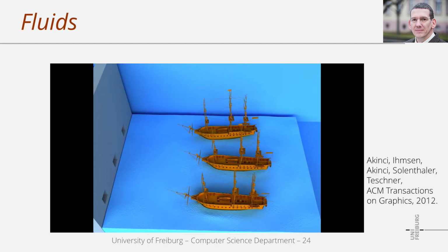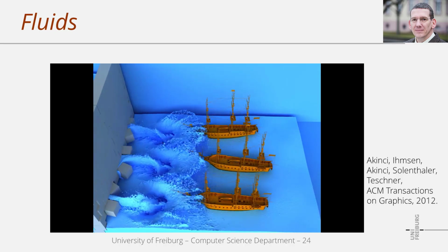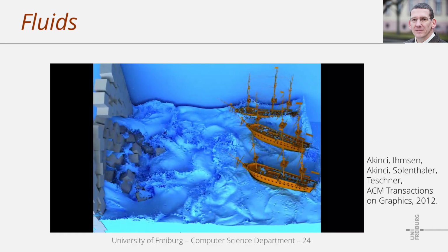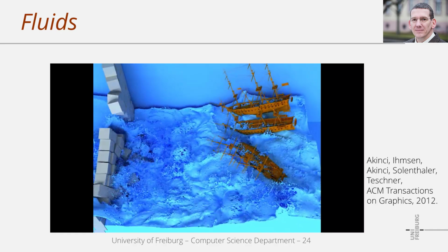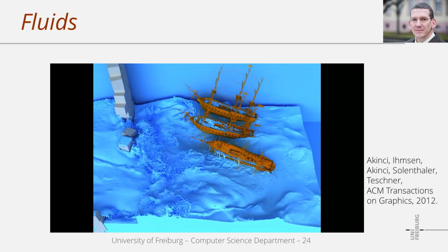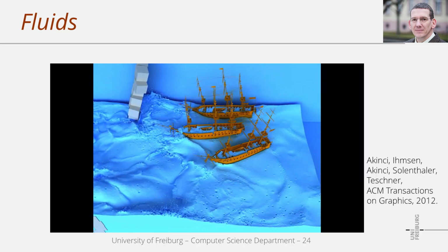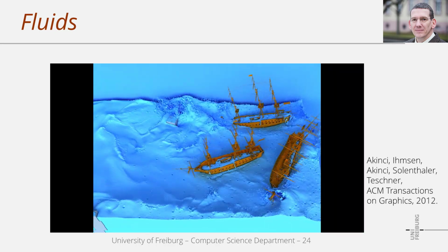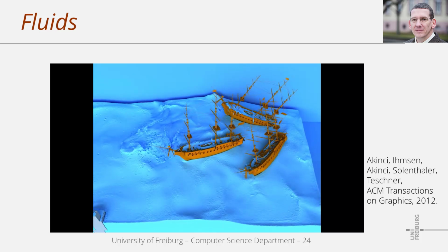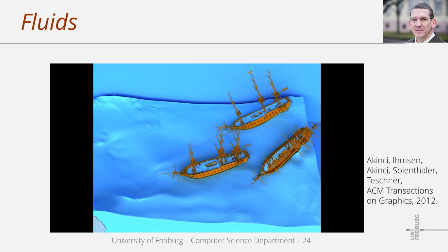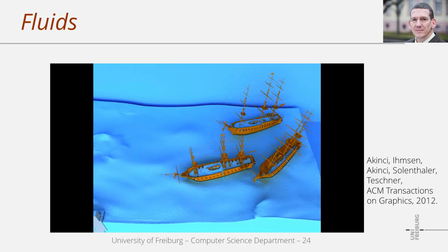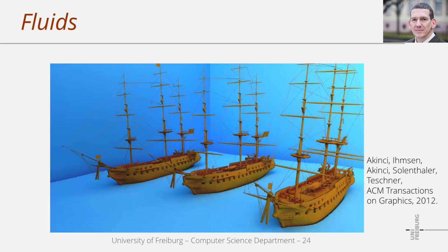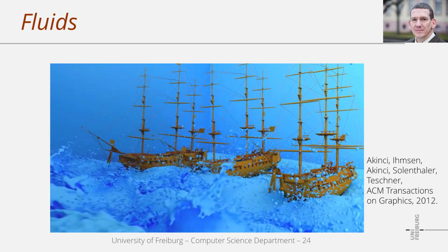Now here we have another example video that shows what we can achieve with particle-based SPH simulations. And once more you can see the focus of our research and also of this course. We are interested in complex, highly detailed simulations. In terms of the fluid, we are typically interested in so-called free surface simulations, where we have an interface between fluid and air, and we are interested in versatile effects. Here, for instance, we have geometrically complex ships that are two-way coupled with the fluid. This means the influence of the ship on the fluid and the effect of the fluid on the ship both are reflected in the simulation.